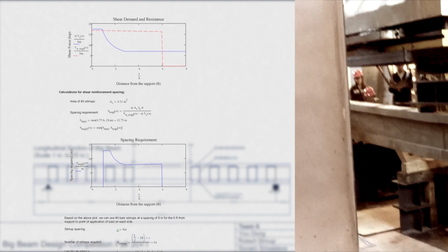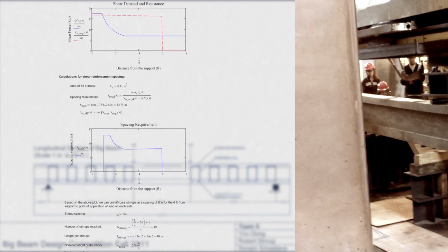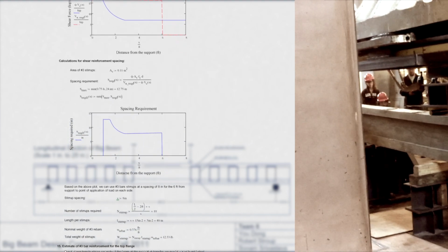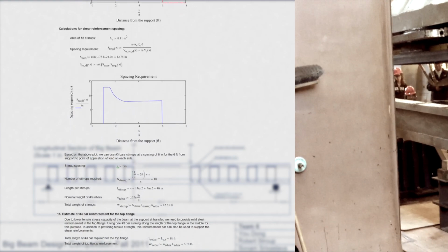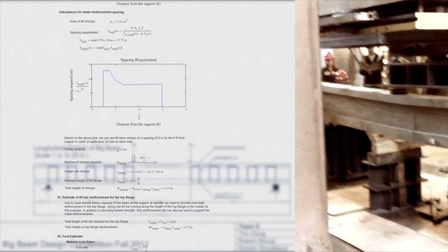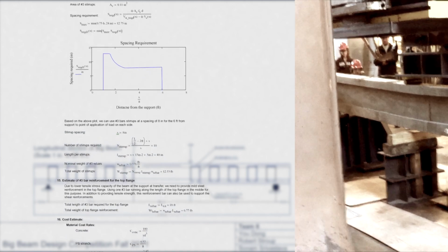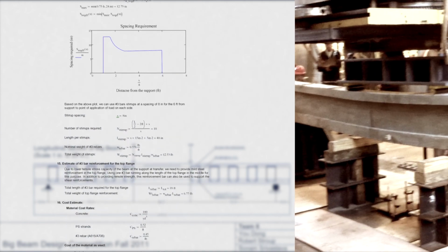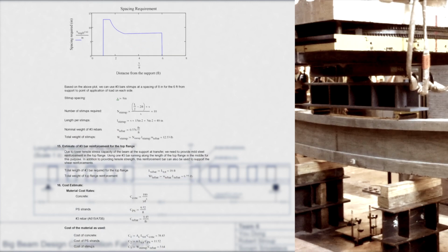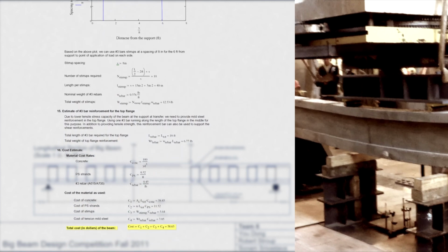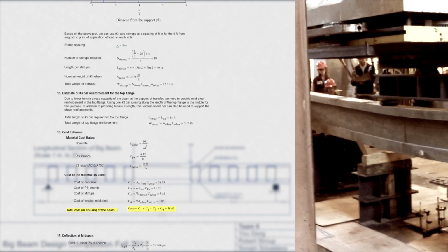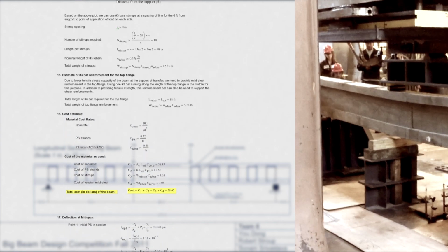Using a strength reduction factor of 0.9, we then found the required moment capacity of the beam was about 99.27 kip feet. After calculating the cracking moment at 65.74 kip feet, we then used simple statics to determine that the live load necessary to crack the beam was approximately 21.9 kips of force. Having only 20 kips of force applied in total, our beam would hold up to the given loads without cracking.